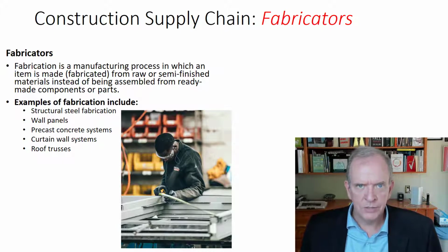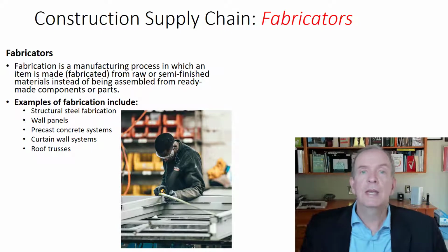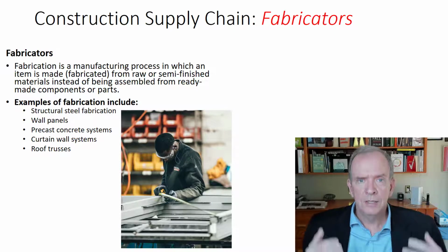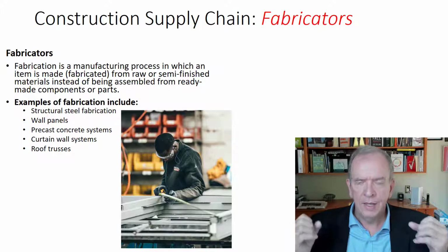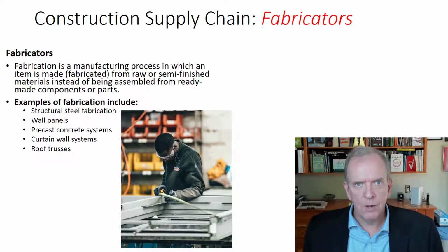So it's economies of scale, so to speak. The other thing with fabrication, if we get things fabricated in a shop, then it's not taking up space on our site. That's a big deal. We're limited on space, and if things get in the way while we're moving around logistically on the site, it takes a tremendous amount of time away from the work going on. So fabrication is a big bonus wherever we can prefabricate things.